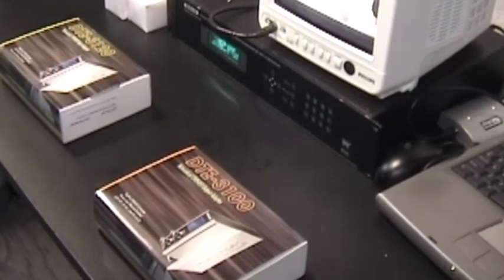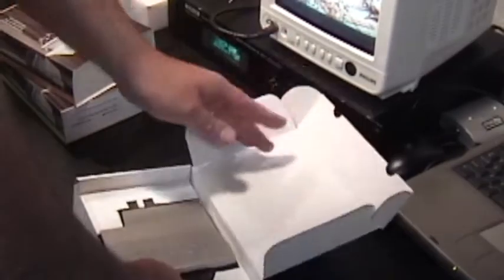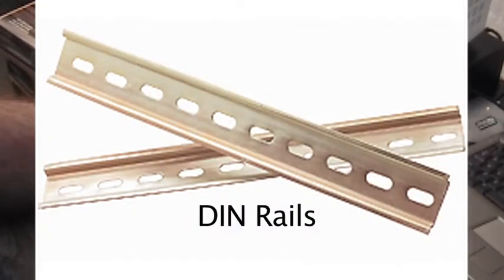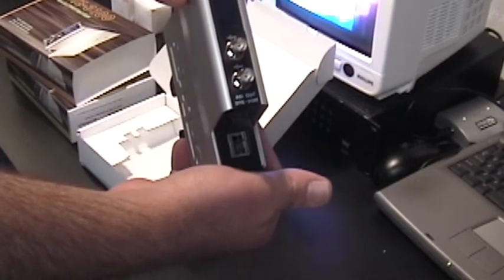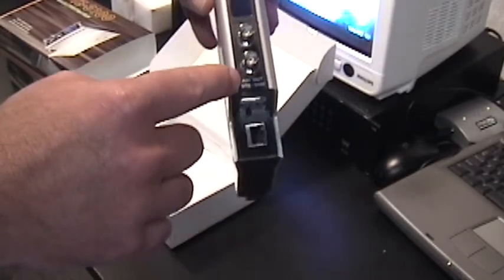After the TSoIP transmitter receivers arrive from Sencor, I unpack them. I start with the receiver. It's a small unit that can be mounted on a DIN rail. Here you can see the connectors. This is the network connector and the ASI output.